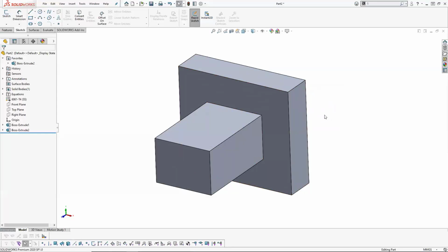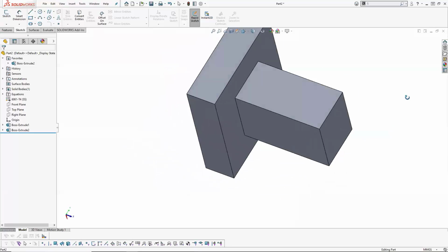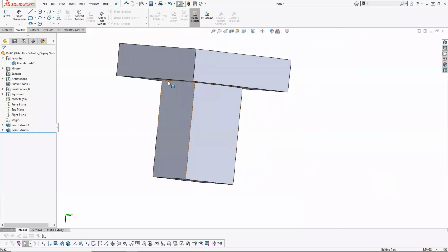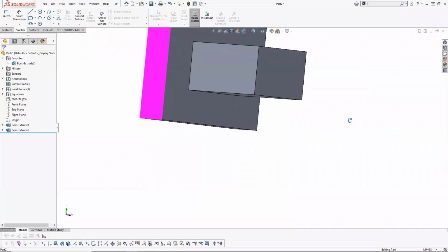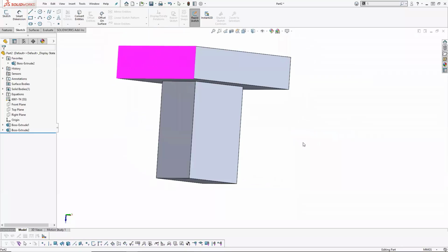So I'm going to go over here, middle click, and then hold the middle wheel down, and now I'm actually rotating about that corner of the model. Same thing if I click on a face. I'm middle clicking, a click and release. That selected that face, and now when I rotate, I'm rotating about that face. That's a little trick on the rotates, but hopefully that helps you with how I'm rotating.